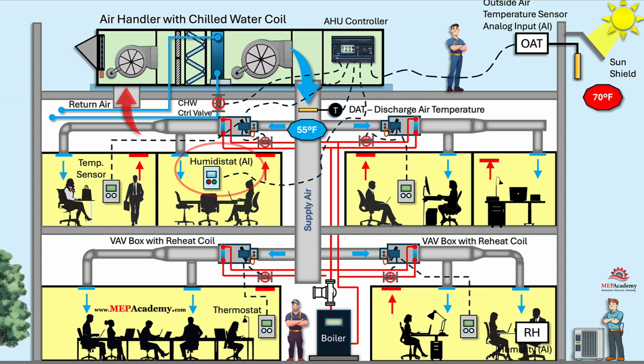An outdoor air humidity sensor can help the system determine whether outside air is suitable for cooling and dehumidification. In humid climates, the system may rely on outdoor enthalpy rather than just temperature to control SAT and ensure effective dehumidification. When a higher SAT is implemented, the system continuously monitors the outdoor or indoor humidity levels via sensors and humidistats, or both. If the RH exceeds the preset limit, the system either halts the SAT reset strategy or adjusts the SAT to a lower value to maintain effective dehumidification.